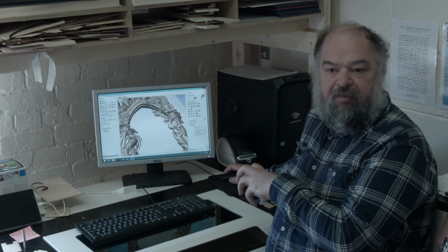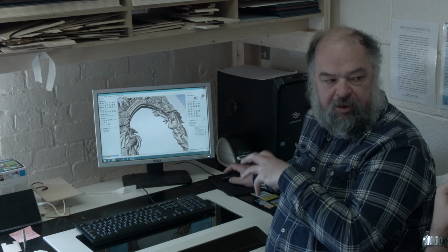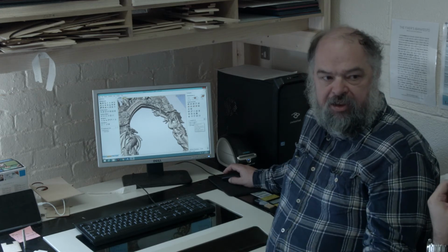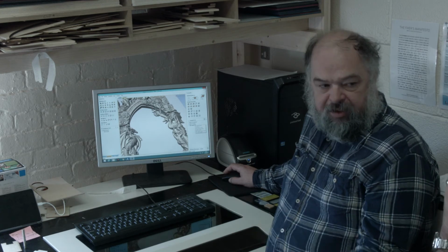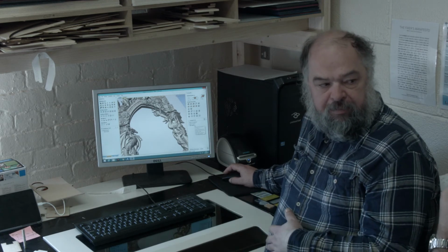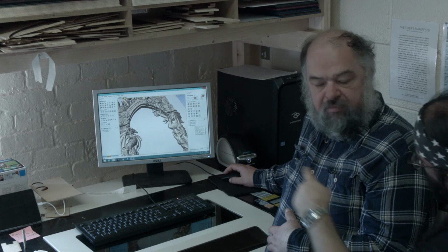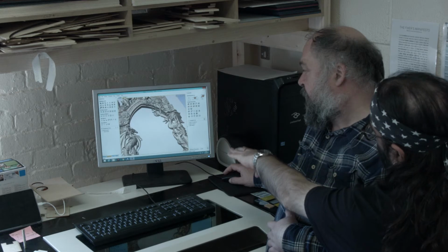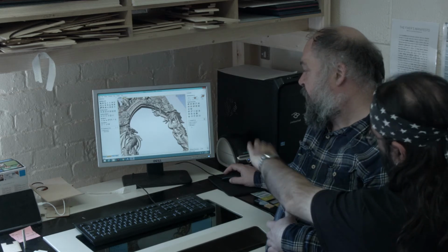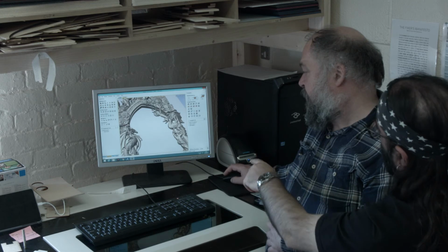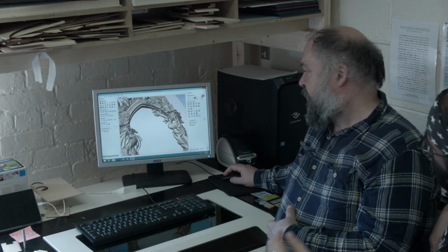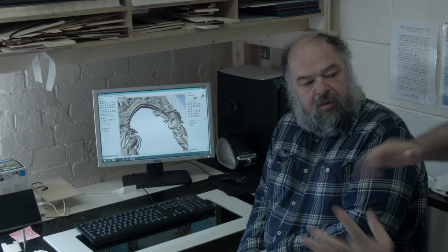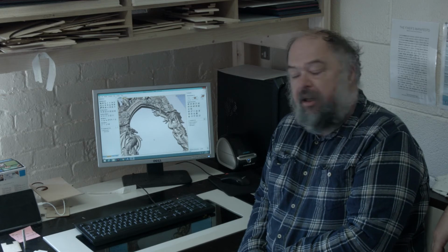So that you then, if you've got a tool changer on your machine, you can have it set into 1. But if you haven't, what it'll do is it'll run that one, then you'll change a tool, it'll run the next one, change a tool, run the next one. So my question was is it piling up there? And I see it is. You have the 3 operations that you've done: the roughing, the finish, and the profile, which is removing the bits that you don't want. And if the machine has an auto change thing, it's one big G code, one big file, and then it takes care of that.